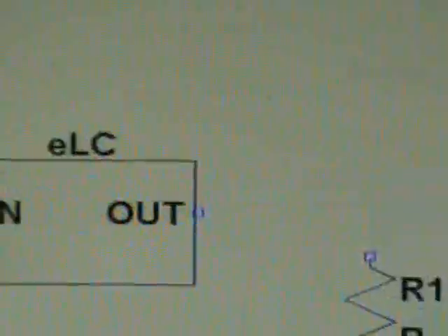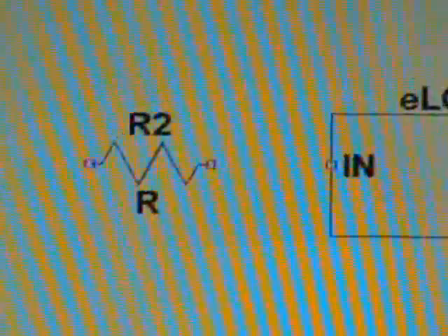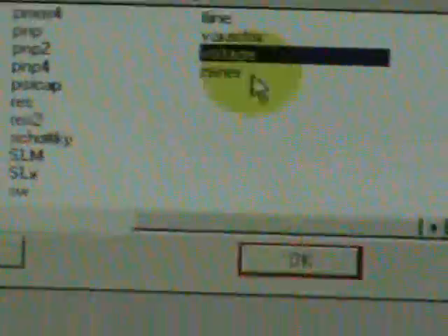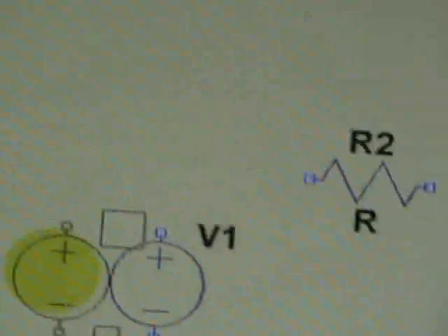Now let us drop the resistor. We can either get the resistor from this collection, inductor, diode, component, or you can pick the resistor from this position. Let's drop it here. Now we like to put one horizontally on the left side. So we select rotate, put it here. Hit escape key, drop an analog ground, hit escape key, go back to component, pick the input generator, which may be sine wave, piecewise linear, exponential, FM, sweeping, signal, DC, AC, pulse, sine wave source. So we drop the generic symbol, hit escape key.